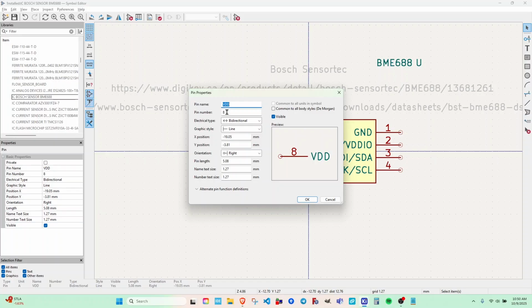That is crucial to understand. That's how KiCad knows to assign which electrical connection to which pad. And you can name this anything you want. You can name it letters, like for a diode, you'll sometimes call it A or K for anode and cathode. You could call it HJK. It doesn't matter, but it has to be the same on the schematic symbol and on the PCB footprint pad. So something very important to keep in mind. And you'll see that when we go over to do the PCB footprint next.